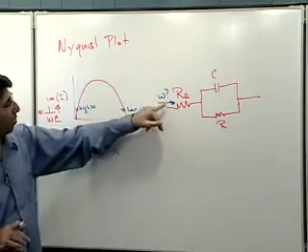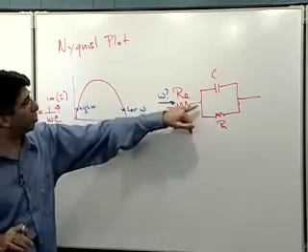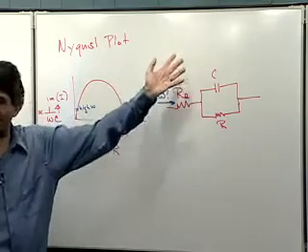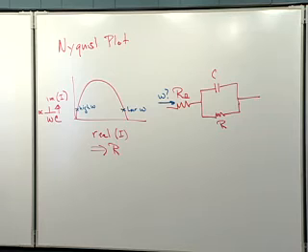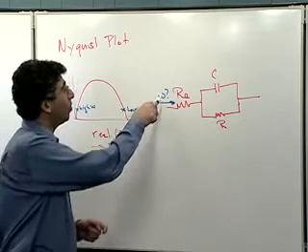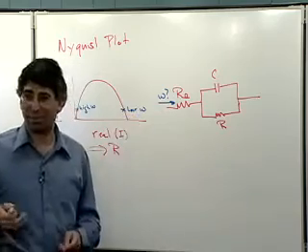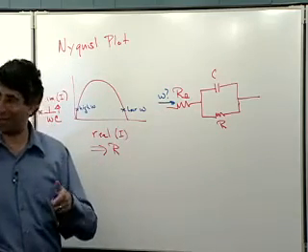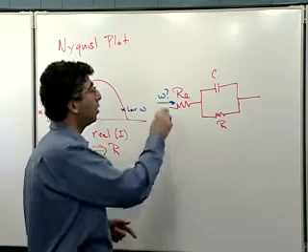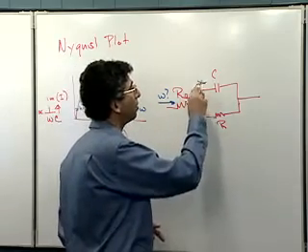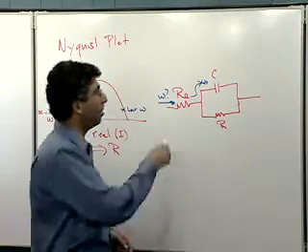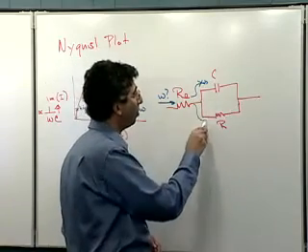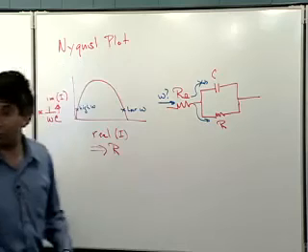And when the perturbing wave gets to this point, it's got to decide whether it goes up or down. And it's going to make that decision simply based on the lowest resistance path. You know that if this frequency is very, very low, let's say it's DC, a frequency of 0, then this path up here is blocked, right? You can't get through a capacitor with a DC current.